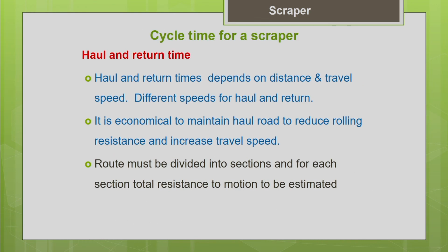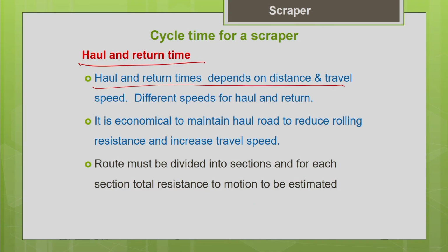The next important component of the cycle time of the scraper is your haul and return time. As I told you, it is variable time. It is going to depend upon your travel distance and the speed of your machine. That speed depends upon your project site condition, underfoot conditions. So, haul and return time depends upon the distance and the travel speed.